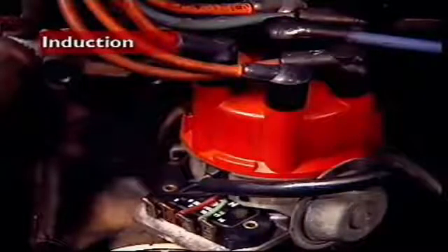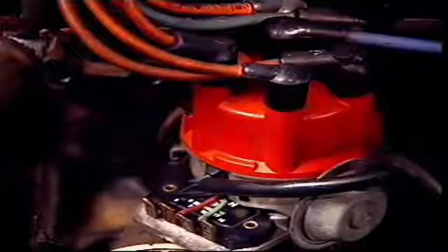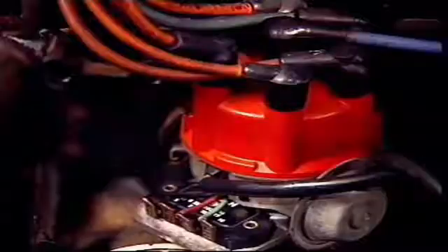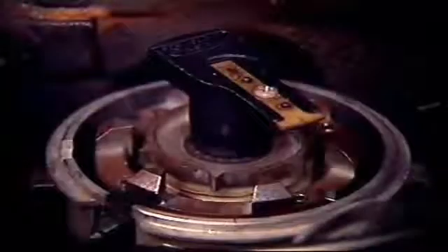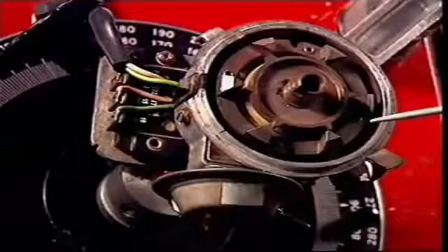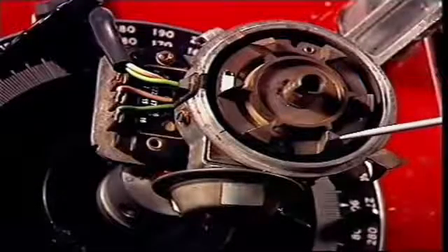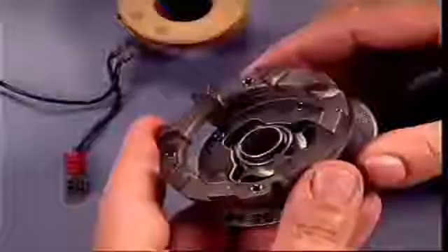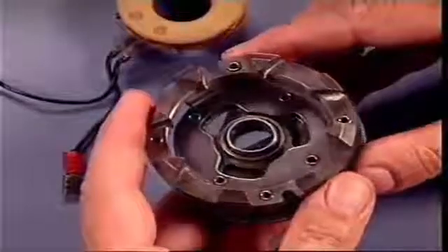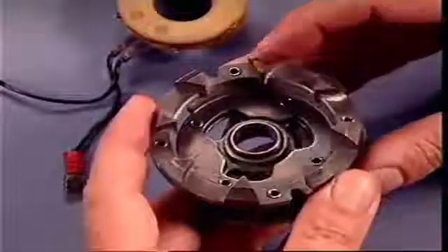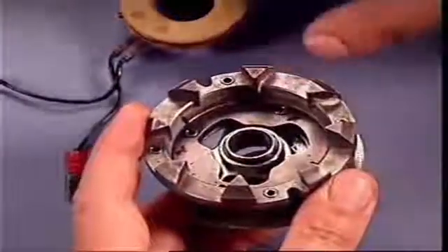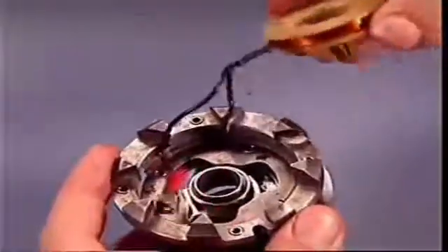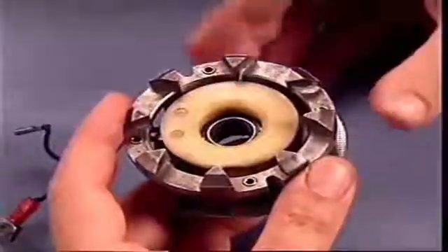In electronic ignition systems, the contact breaker is eliminated and the switching or triggering of the primary circuit is carried out electronically. In induction type systems, a pulse generator has a stator mounted on the distributor body and a rotor unit called a reluctor attached to the distributor shaft. The stator has a circular permanent magnet with a number of projections or teeth corresponding to the number of engine cylinders, and a stationary coil of fine enamelled copper wire wound on a plastic reel and positioned inside the magnet.